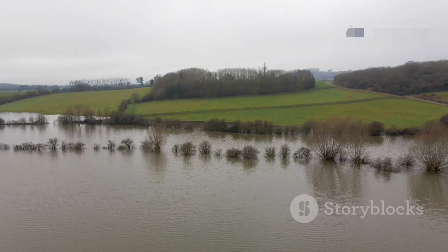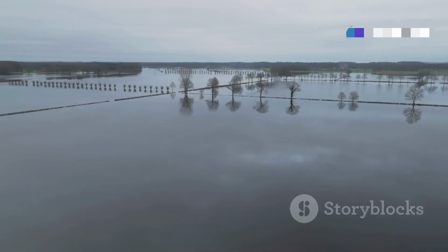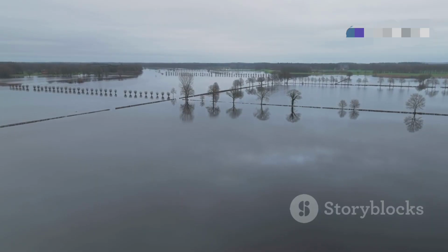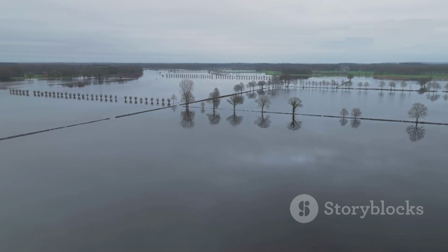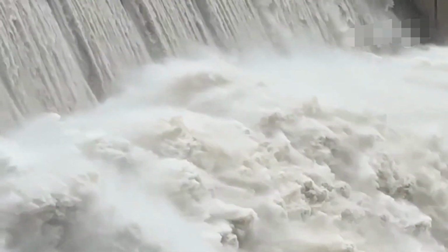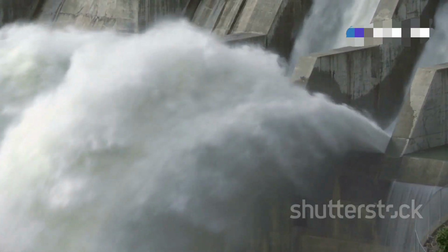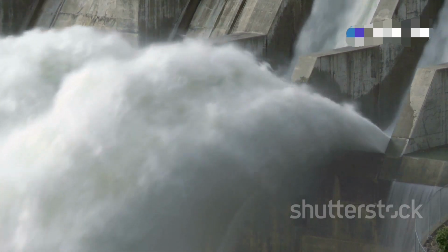The results of a dam break model are highly sensitive to the chosen breach parameters. Small changes in these input values can lead to significant differences in the predicted peak flow, flood extent, and arrival times. For instance, a faster breach development time will typically result in a higher peak outflow. A wider breach will also release more water more quickly.